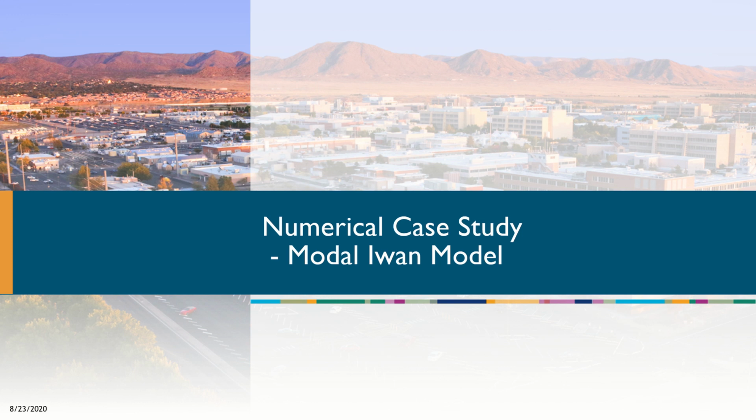And now I'll go over a numerical case study to show what this process can do under ideal conditions. So what I have is a modal Iwan model, which is a single degree of freedom nonlinear dynamic system that has been found to closely replicate the damping and stiffness behavior of a bolted joint in microslip.